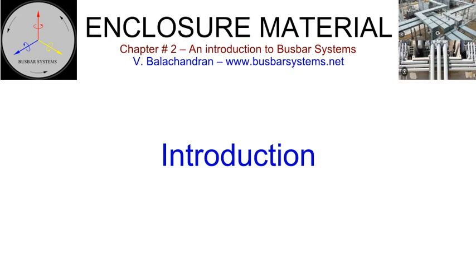Introduction. The enclosure material for an enclosed busbar system is generally aluminium alloy sheet, extrusion, or sheet steel. Stainless steel and fiberglass enclosures have also been used for very specific requirements. The enclosure contributes a significant part to the overall cost of the product and must, therefore, be optimized. The enclosures have to be fabricated, painted, assembled with components, installed at the site, and should require minimum maintenance for the entire life of the enclosed bus.